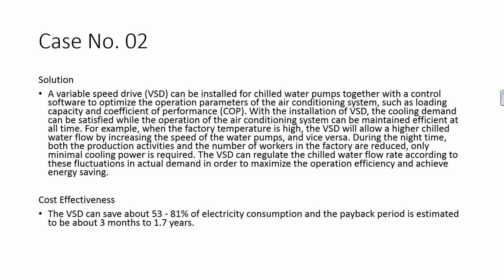During the night time, both the production activities and the number of workers in the factory are reduced. Only minimal cooling power is required. The VSD can regulate the chilled water flow rate according to these fluctuations in actual demand in order to maximize the operation efficiency and achieve energy savings.